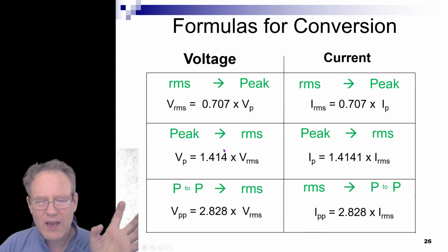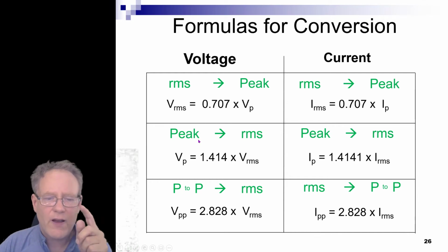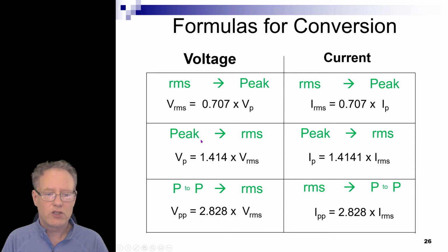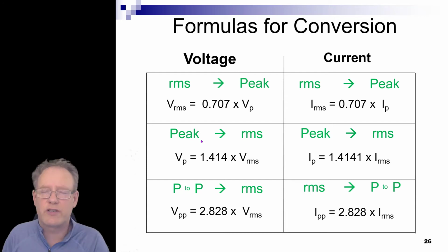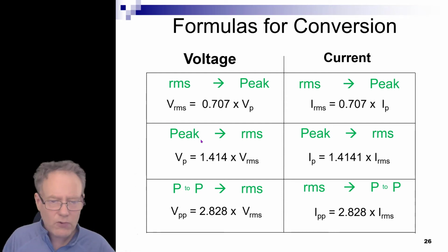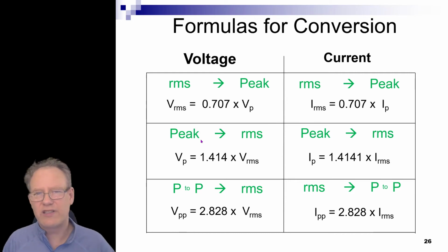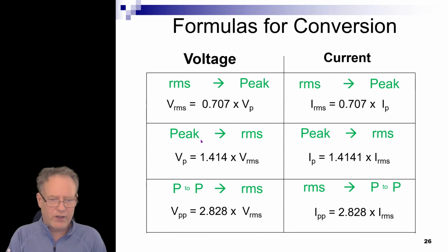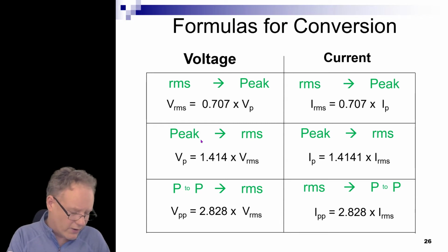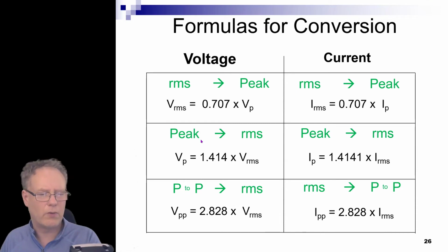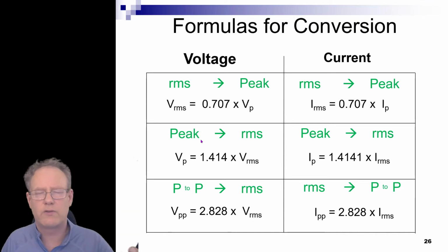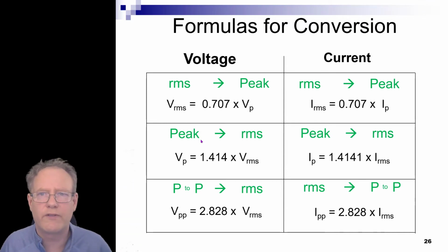And this is intuitive, I think, if I wanted to know the peak. So what's the peak voltage? If I took my RMS, well, I could just multiply it by the inverse of 0.707, or by root 2. So I take my value, my RMS, let's say 110, and I multiply it by root 2, and then I get 155. Remember, the other one was 156, and that's actually 155.56, so it's 156, whatever, same.